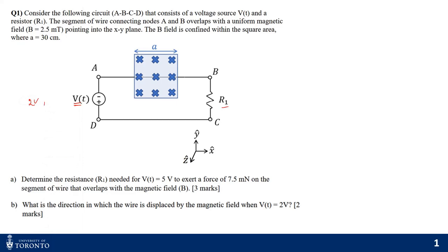Then the current should come out from the positive terminal, right? And according to this circuit, it should go anti-clockwise, right? But let's say if a minus voltage is applied, that means the current should come out from the negative terminal, right? And it should go clockwise in this circuit. And the amount of current I will be given by V by R1 in this case, right? Which is this resistance.